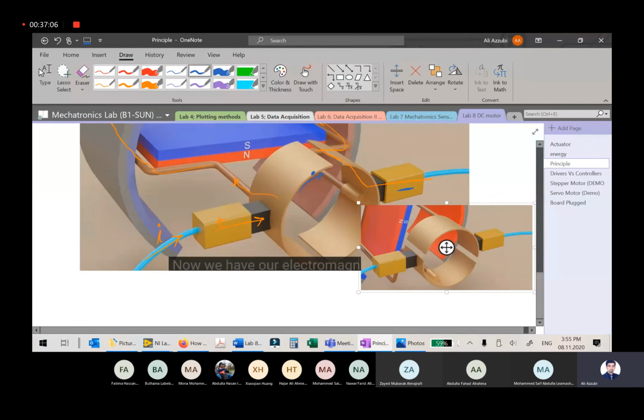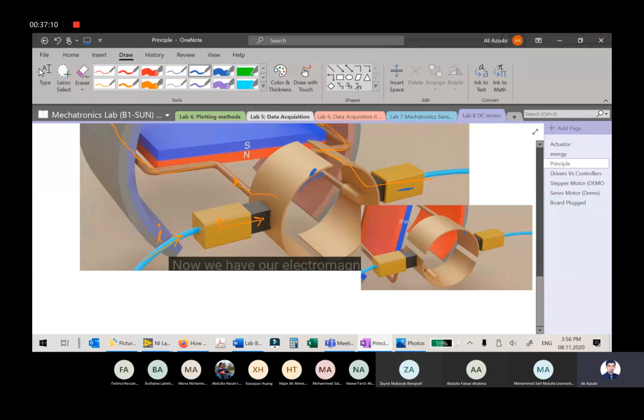Now you see at this point, this pole here has become here. Previously it was positive. Now when it comes here, it will become negative, and this is positive. Now this means the current was flowing from this side, this brush, inwards. Now instead, it will go from this side and come back like this.